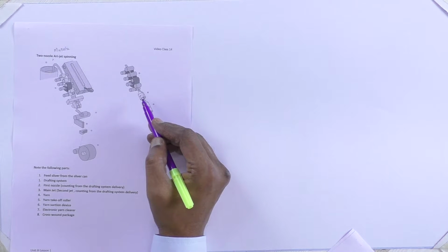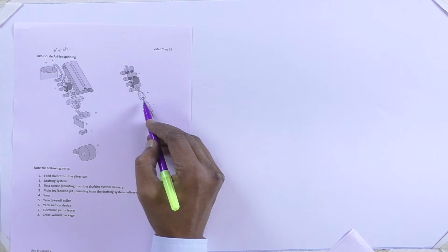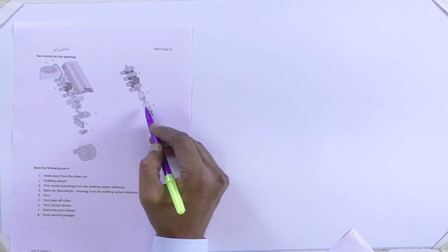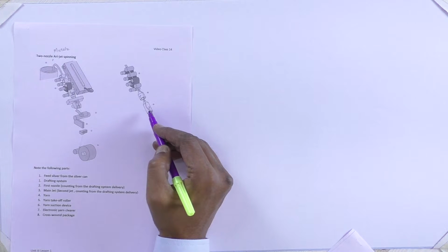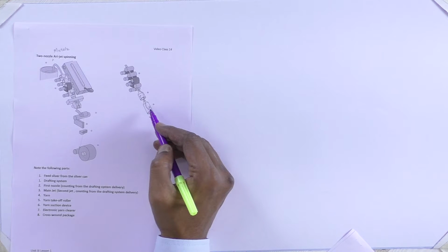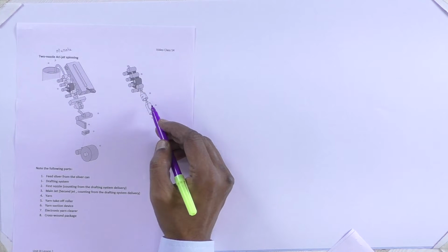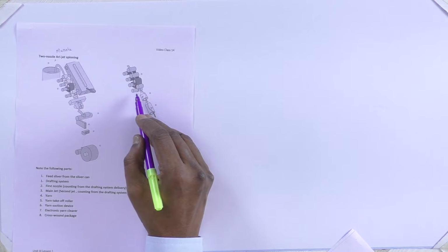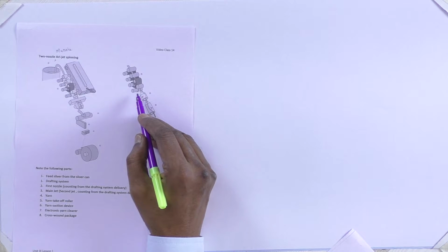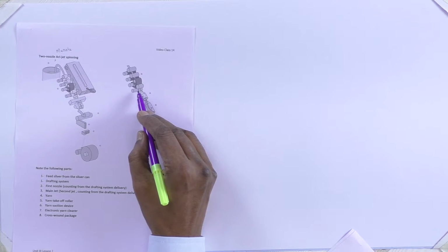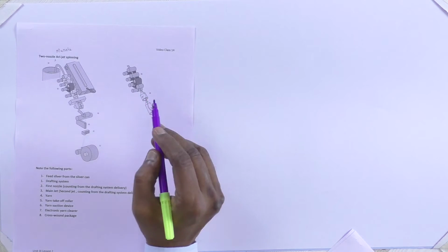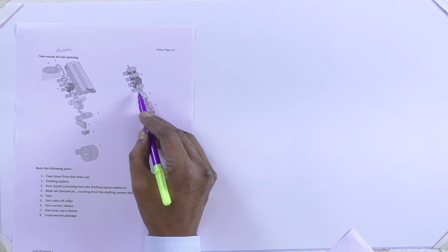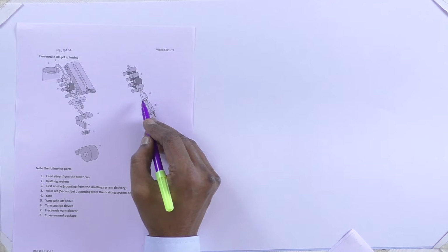These edge fibers are twisted slightly in the direction of core fibers here. Some fibers are likely to be twisted in the opposite direction too. Now, how is this achieved? This is achieved by two factors. The delivered strand is in a broad ribbon form, that is one control aspect, though the realization of the twist in the edge fibers is rather less. Though we are having a wider width that produces edge fibers, the effect is rather less.